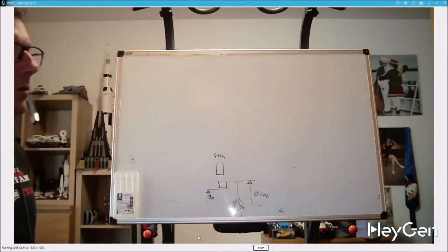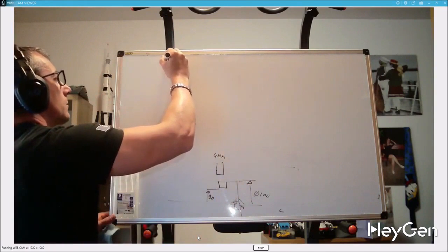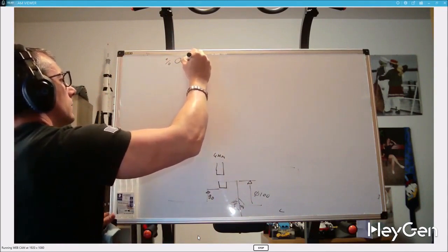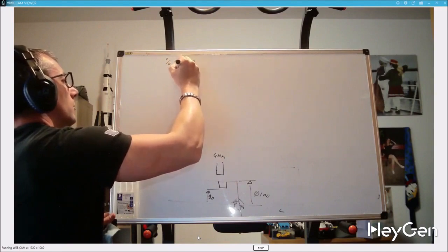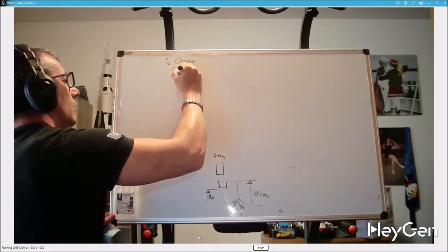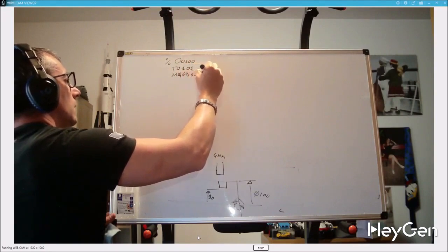In this example, I am creating a subprogram for a CNC machine. It starts with a percentage sign and 00100, the program number. I call the turret with T0101 and use M4 to start the spindle. G96 sets the speed to S100. The machine moves to position